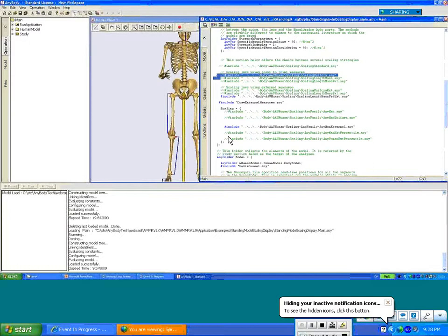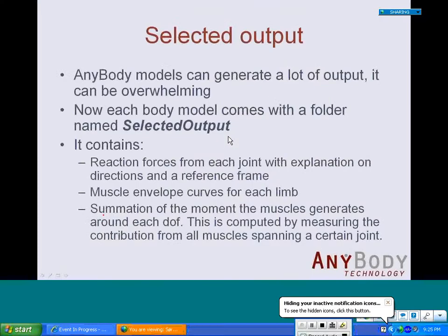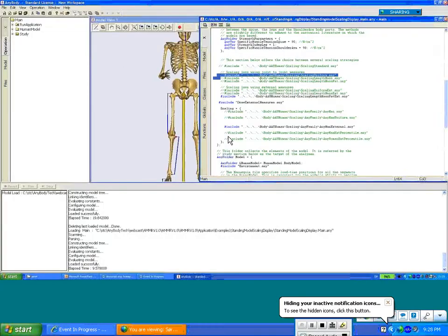Basically, if you look at this first line here, there is the scaling uniform. It's the one that scales equally in all directions. And then the second one here is the scaling length mass, and the last one here is the scaling length mass set. All these three scaling laws, you can only have one of these active at a time. And together with one of these scaling laws, you would also need to have a definition of the segment length.